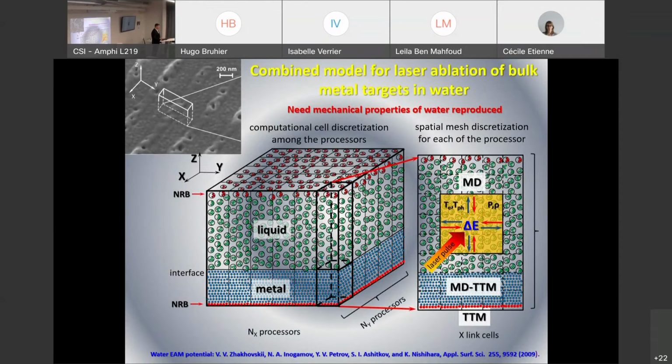The reason is to keep high efficiency of calculations. Instead of 3 particles, we only process 1 particle. Of course, in this case, heat capacity is underestimated. But what we believe is that most heat losses occurring during the cooling of the growing feature will be due to heat of vaporization, which is much higher than the heat capacity value.